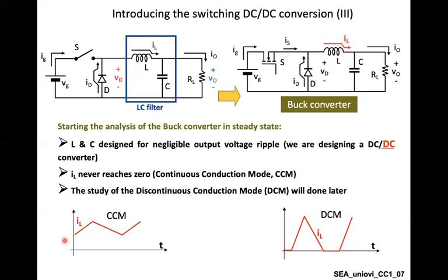So in this portion of the signal, the current in the coil is increasing because it's connected to the load, till we reach a point where we reach a maximum. Then a low signal comes to the switch. This switch will turn off, I mean disconnected. Now the energy in the coil will start to discharge in the resistance and back through the diode. So this will make the current go down again.